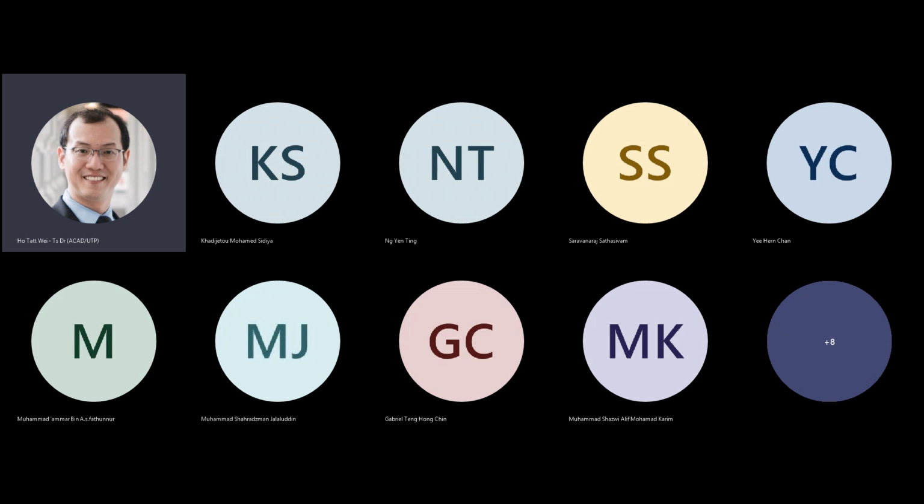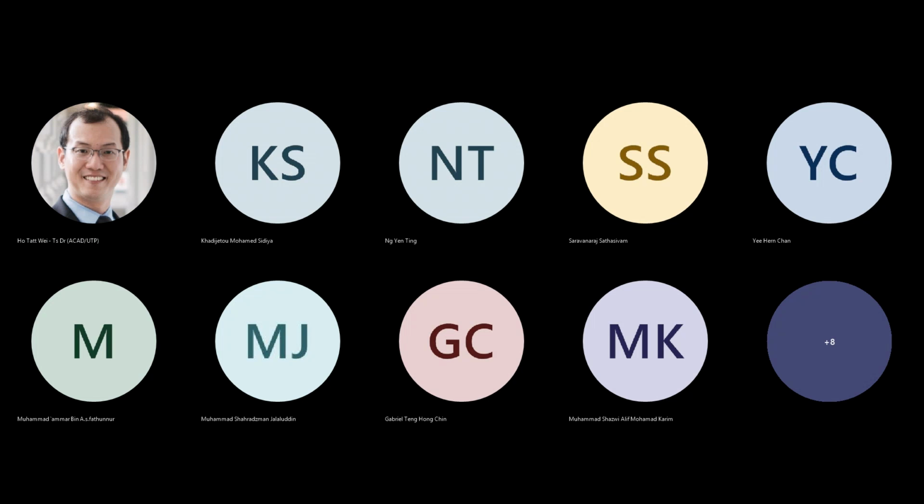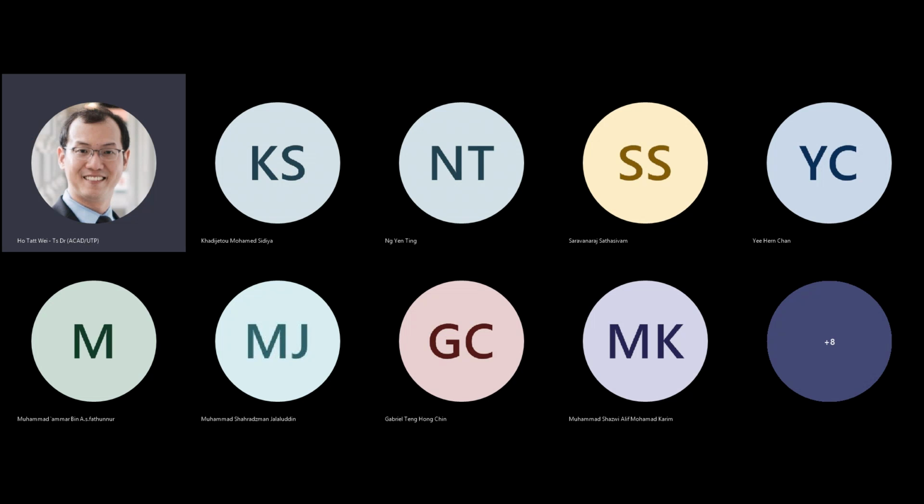And there is a maximum clock speed at which you can run the entire design, right? So your clock has a period, T, okay? And there is a minimum period at which you can run this design. If you try to have the clock come in at a faster period, that means the switching happens faster, and this design will fail.